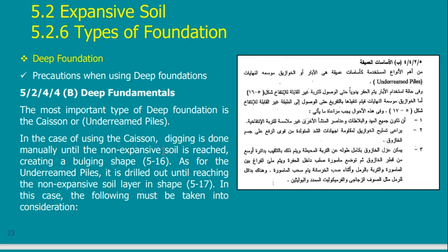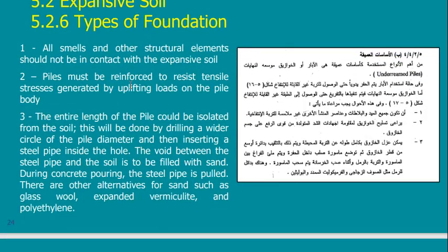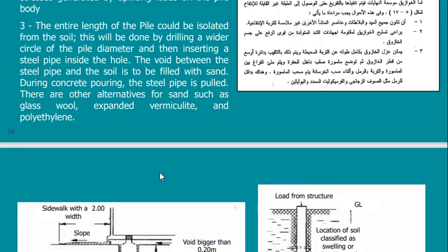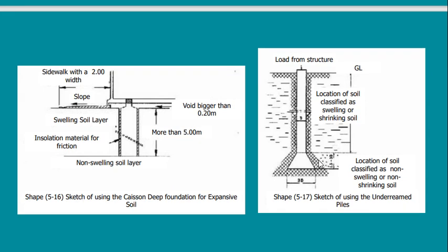The best thing is to replace it with isolated footings, with very rigid tie beams. Pay whatever you want to pay in increasing the rigidity of the tie beams, or use a raft with very big openings. It will be much better than this. This is what we have said before. These are the piles with the enlarged base that I was speaking about.